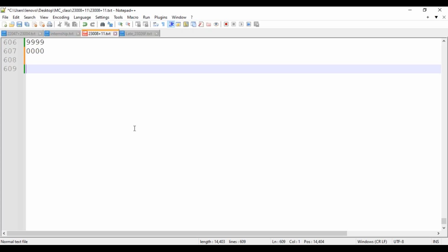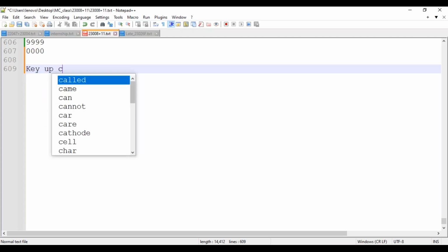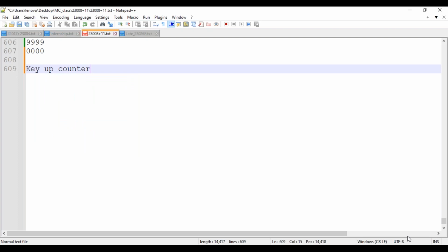Okay. Now let us do a small classwork. I have to implement a key press counter. So what kind of data do we store in EEDATA? Whatever data you want to write into the memory of the EEPROM, you have to write the data into the EEDATA register. Only then will this register have the data written into the EEPROM. In whatever address you want to write, I have to write it into the address register.